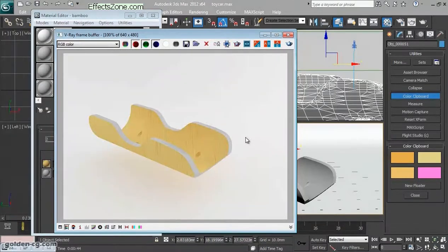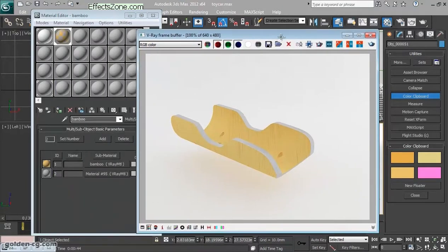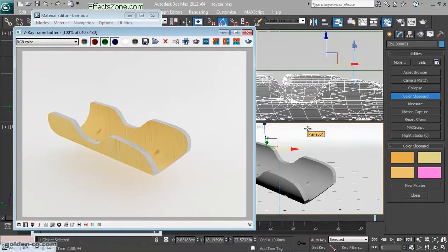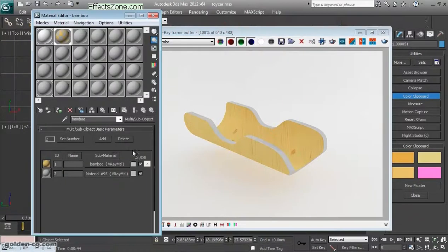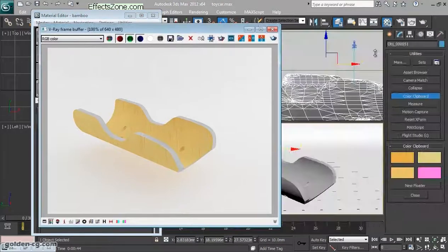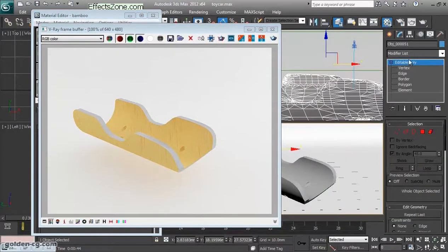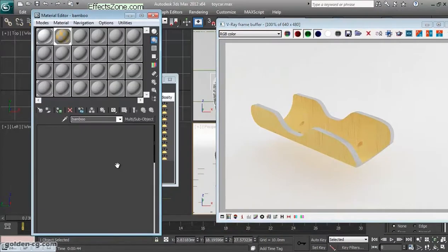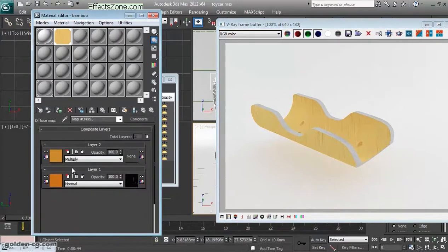and here is the result. Another problem is the direction of these lines. We need to rotate them, but because our object has some problem, it is already imported, so we cannot. And also we are using procedural maps, we cannot really use the UVW map. Our UVW map will not work, so we need to rotate it in here.